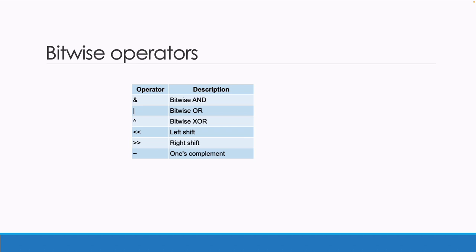we just want to, for example, in the case of an output, set a specific output. We want to turn on the specific output, or we want to turn it off. Also, in the registers, we might want to enable one bit in the register of the microcontroller, or we might want to disable the bit. We can do this using bitwise operators.